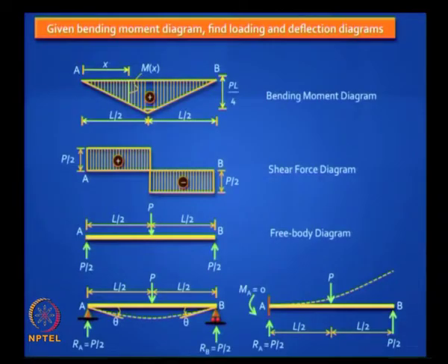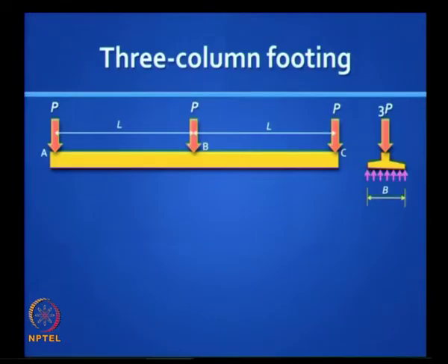So all you need to do is to have a rigid body rotation of one diagram. The curvature doesn't change, but the deflections change, and that's what you do. You rotate this first diagram anti-clockwise by theta, and you will get the other diagram. So it's very important to understand these relationships. So that's 2 theta at the free end of the cantilever.